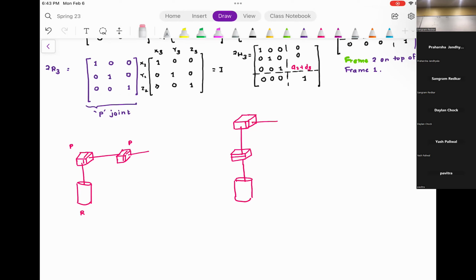Every time you get a robot, before the kinematic diagram, you have to identify anything that is varying; that is a joint. There are two types of variation possible: linear variation and angular variation. If you have a spherical joint like a shoulder, we approximate it as the first, second, and third revolute joints on top of each other. For kinematic diagram purposes, we have to split the robot arm into prismatic joints and revolute joints.